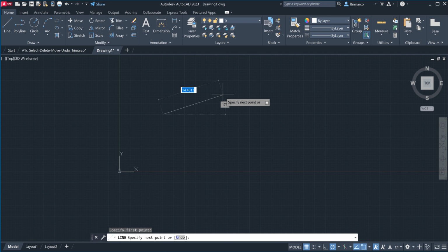And then right away, I didn't bring this up, I am looking at some constraints. A couple things are happening. You're seeing these dashed lines and angles and degrees. Anytime I move my cursor, it's going to show me the degree that I'm at, literally. Right now you see 28 degrees, so if I snap on the left side of my mouse, I will have drawn a line 28 degrees from its start point. However, you're also seeing a little flag highlighted in blue that says 10.0949. Right now, my template file in AutoCAD is set to a decimal unit, not architectural.